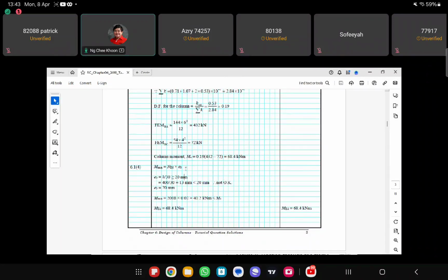And then, as I mentioned just now, we need to calculate the minimum moment, right? We do not need to calculate imperfection moments because the instruction says ignore imperfections. But minimum moment is compulsory. So minimum moment is based on h over 30, the eccentricity of h over 30. So we are calculating for z-axis bending, then h is the larger dimension, right?